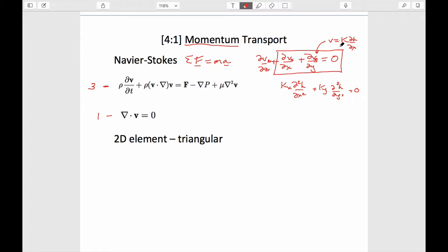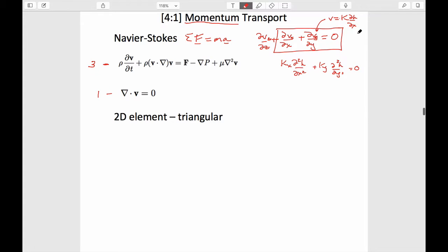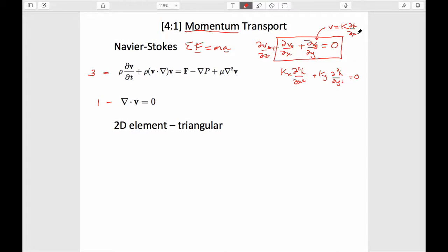And so that's the difference between those systems. So you can't use Darcy's law to solve open channel flow problems, for instance, because it's not going through a porous medium, it's sitting on its own, and so you could imagine that there is really no concept of Darcy's law that you could apply in that particular case. So momentum transport is where we solve for the system of equations without Darcy's law, and actually, as a consequence, take care of the changes in momentum within the system.